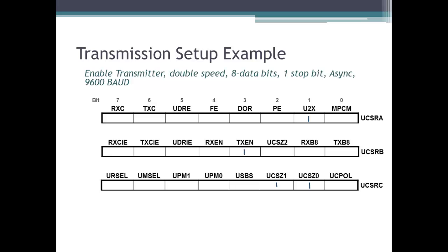And if you look through the datasheet, it also recommends setting bit number 7 of UCSRC high, the URSEL select mode. It says when writing the UCSRC to write this bit as 1. Now it actually has an initial value of 1, but to be safe, you can write it as 1.